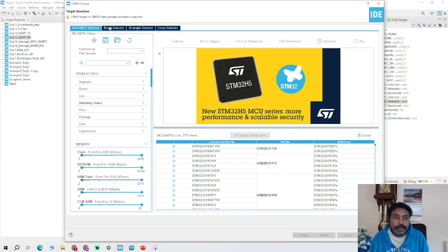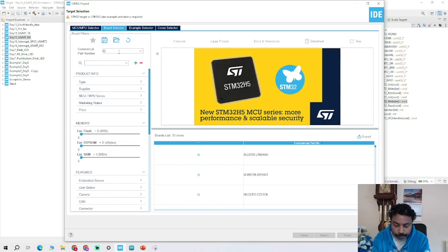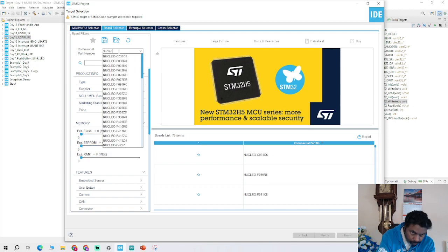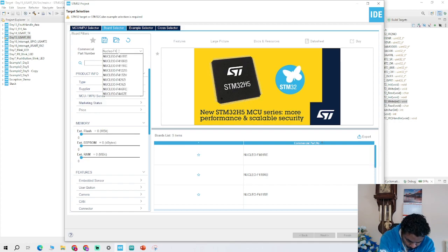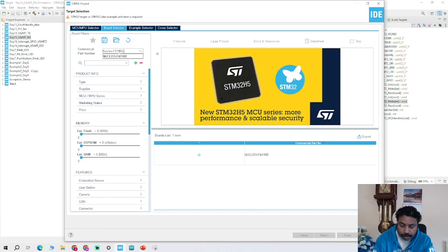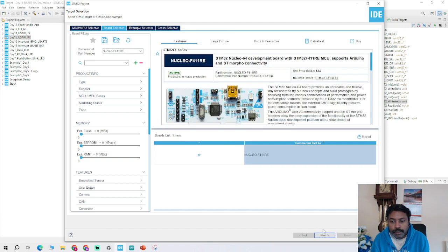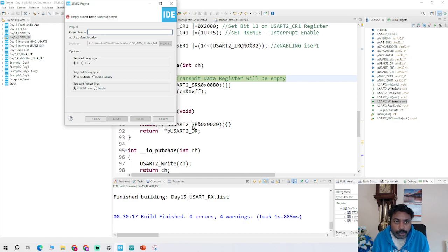Okay, go into the board selector, and we are using the Nucleo board. So just type Nucleo-F411RE and choose that board, hit next and give a project name. Today we are on day 17, so I'll represent that, day 17, and give it SysTick, and start from scratch. I'm going to choose the targeted project type as empty and finish.